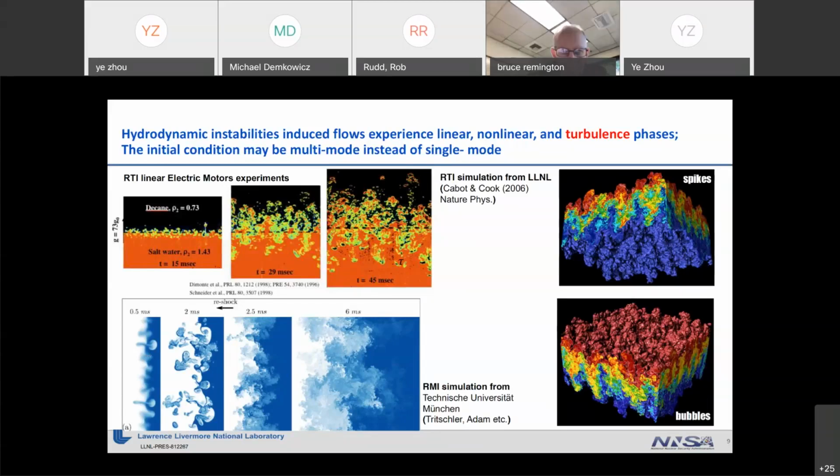When you have a shock wave, such as in a shock tube, the shock wave bounces back from the wall of the shock tube and hits the interface a second time a little bit later. That's often called a reshock. That makes the mixing layer become turbulent much faster. So basically the reshock speeds up the transition process to turbulence.